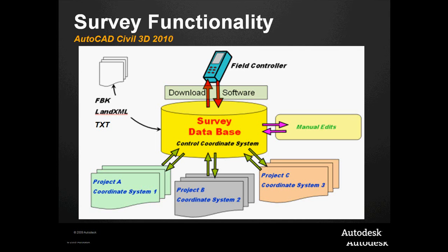So, finally, the database itself, a coordinate system can be applied to that. What's beautiful about that is I can now transform things on the fly. So by connecting a drawing to this database, a simple drag and drop operation, if this is a state plane projection, and I have to integrate with data that's at a county or something that's metric or some system that I'm not currently in, I can connect the drawing to my database, drag it into the drawing, and transform it on the fly. I don't have to recompute any of my data. It will immediately go from state plane to metric. And if they have data in their file, I can grab that, drag it into my database, and it will transform it the other way as well. Okay, and we'll take a look at a quick example of that.